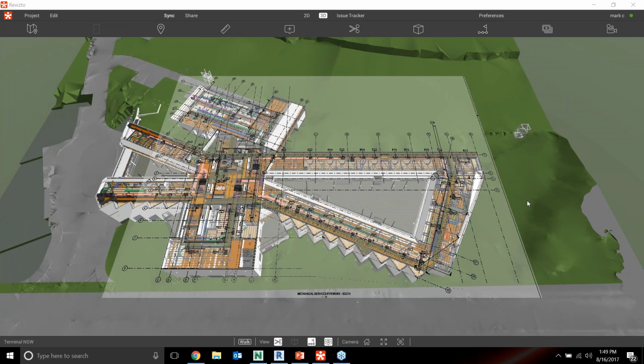Can it be due to something we're doing wrong in the export screen? So if you have rendered appearance checked, it could be part of the export process. It's going to override some of those. But if you change materials in Revit and you're re-exporting the model, those should be reflected back into Revizto. Same with RPCs, ArcVision content, all that stuff should come into Revizto.